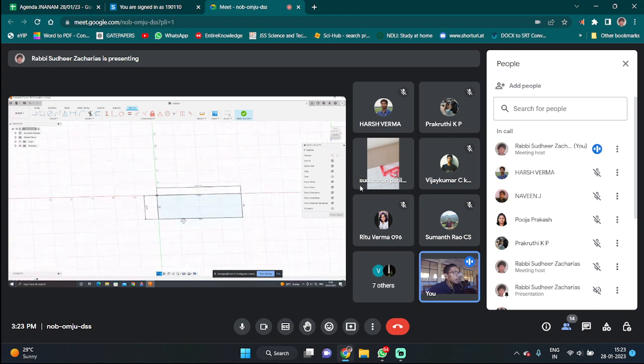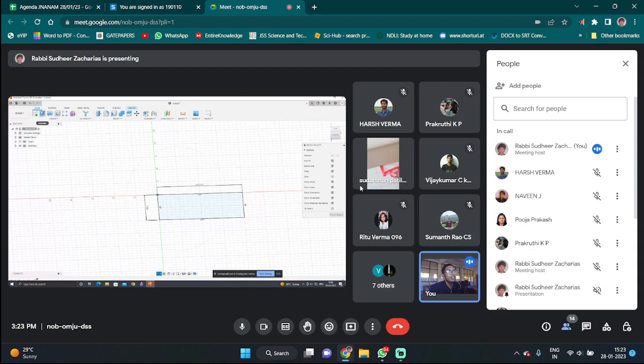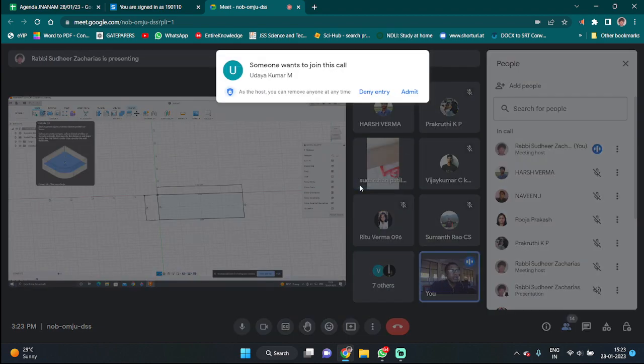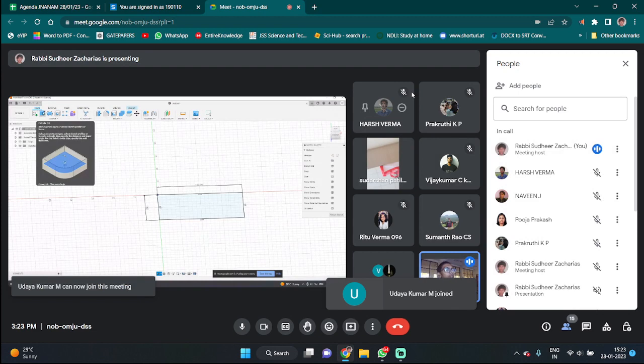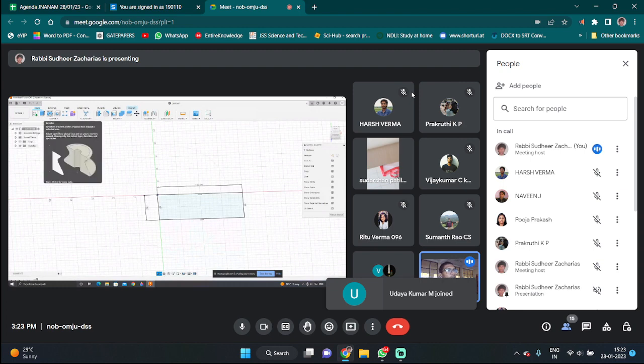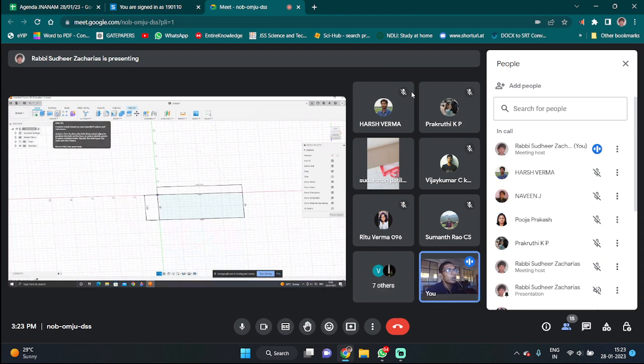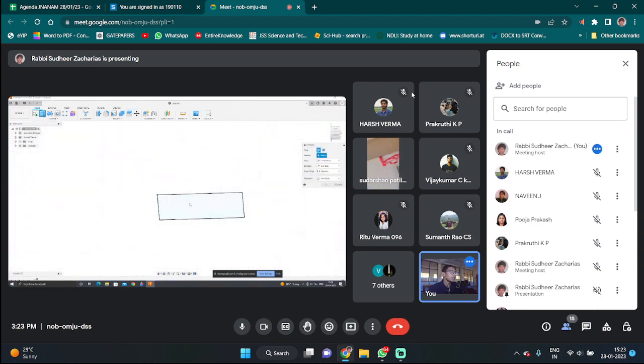Now we need to start placing 2D structures so that it will become a 3D structure. So we can go to the solid option now once we are done with the 2D structure, and we can click on the extrude option. And without clicking, if you just keep your cursor on top of an icon, it can help you on what it basically does. So here, if you see the hole option, if there is a 3D structure and you want to create any holes, you can use that. But for now, after drawing the 2D structure, we are extruding it.